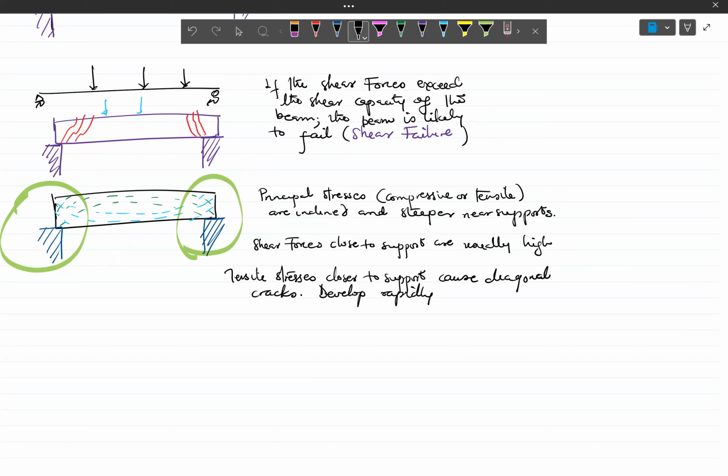And this is the reason why, when it comes to design, we are very critical about shear, because when you compare shear to bending, bending is typically gradual, especially when you have designed your beam for the rebars to yield first. The bending failure is gradual. But with shear, regardless of whether you have the longitudinal rebars in there or not, it can be quite abrupt or can develop rapidly, which means that failure can be sudden. All right. And we do want to avoid such catastrophic sudden failure.